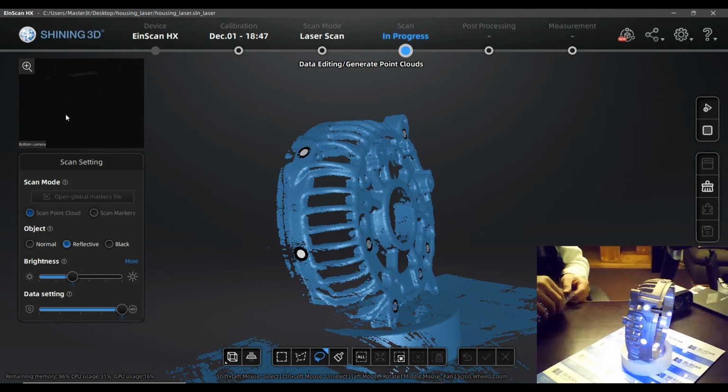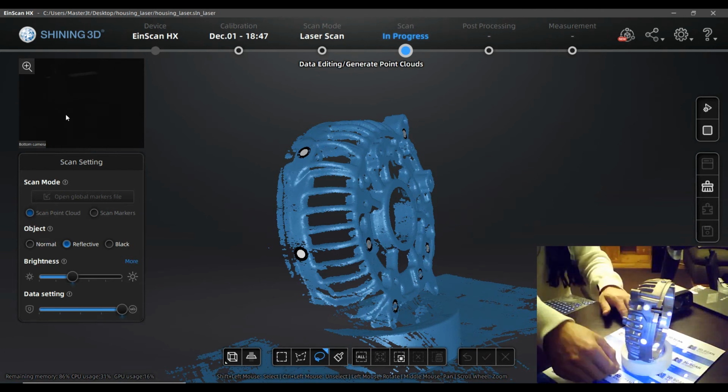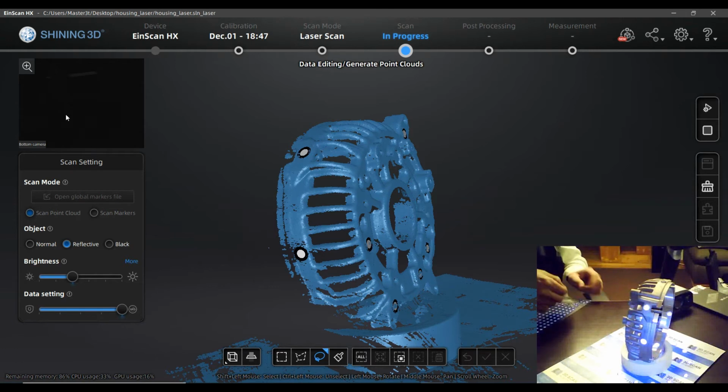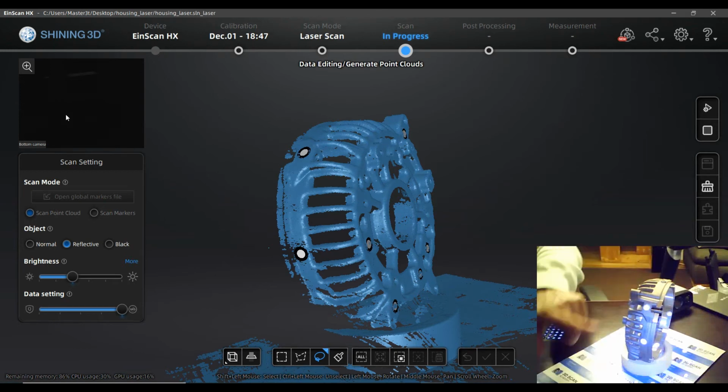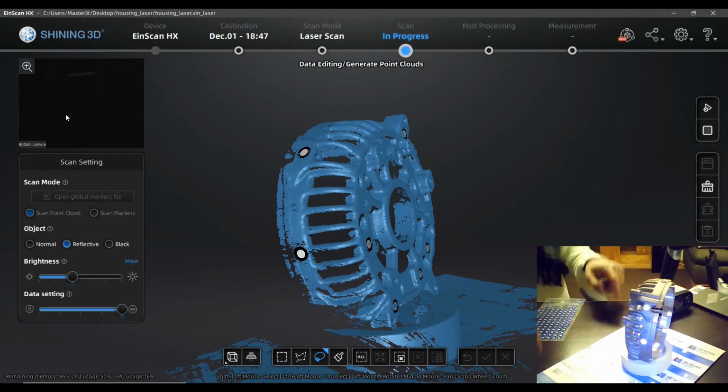Just one more, as I'm not going to remove them with a lot of stress afterwards. I don't care to use more of them. It will make me scan faster and easier, and I will not have to think too much about where to put the camera. Okay, so I have applied quite a bunch of markers around, and of course they have to be in an area where they are visible for the scan field. For example, if I put them outside of the center of the scan, the camera will not be able to capture them, and they will be useless.